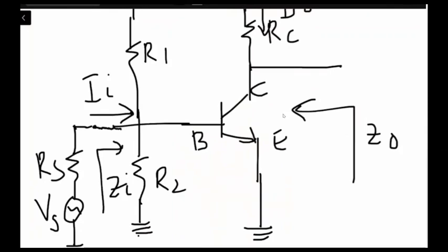Yes sir. You were talking about the capacitor, and then you said something about high pass, and then the voice went away. Okay, the capacitor connected with RE is called the bypass capacitor. A bypass capacitor means it is going to bypass the circuit for AC, and it will allow things to pass through it for DC. So for DC, RE will be there, and for AC, RE will not be there, because RE will just work as a short circuit due to the C3 capacitor. Are you with me? Yes sir. Right?